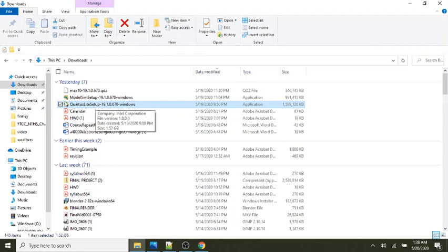However, you only need to basically run the Quartus Lite setup because it'll take care of doing the other stuff. Once you finish Quartus Lite setup, it will have already set up ModelSim, and if you had hardware, it would have set up that device. So the point is, when you download the software, you should have either these two files or these three files, and then just double click on the Quartus Lite setup, and it will install it for you. So that's all there is to it.